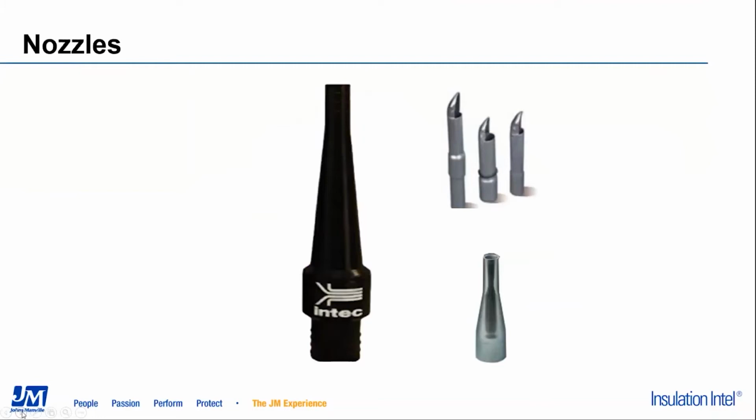So nozzles are very important to the application process. The nozzle attaches to the end of the hose and is placed behind the fabric when filling the cavity. The nozzle allows us to achieve a more even distribution of blowing wool and aids in getting behind wires and around obstacles. The nozzles come in a wide variety of shapes and sizes and are designed for different application processes. In purchasing a nozzle, you want to make sure to ask what type of application the specific nozzle is used for.